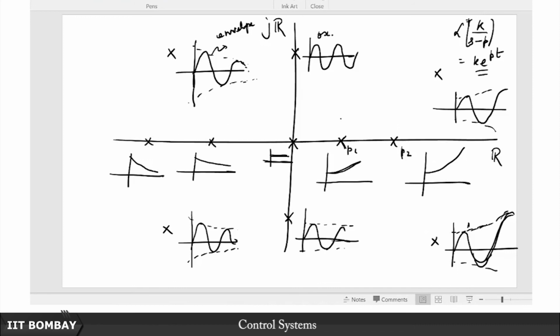Similarly, anything to the right is clearly unstable: depending on whether it is real positive or complex conjugate, it will be either purely divergent or oscillations along with divergent behavior. But it is this curious case of poles on the imaginary axis where the jury is still out.